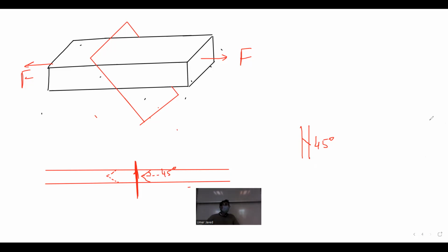I will add you. Also, I have a question about bearing stress. When we're dealing with bearing stress, we're just looking at the projection. Yes, exactly. Because the force distribution is like this, this arrow cancels with the left, this cancels with the left, so the resultant force is acting like this.